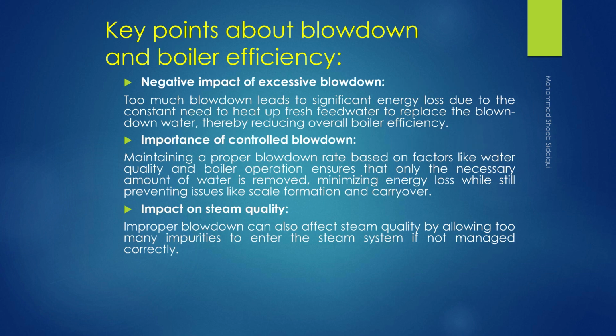Key points about blowdown and boiler efficiency. Negative impact of excessive blowdown. Too much blowdown leads to significant energy loss due to the constant need to heat up fresh feed water to replace the blown down water, thereby reducing overall boiler efficiency.